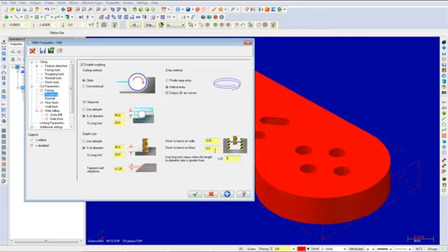I will now explain a few of these parameters. Cutting method allows you to set the direction which the tool travels in. XY step over sets the spacing between passes in the X and Y axis for the FBM generated toolpath type. Use defaults uses the XY step over defaults defined for the FBM generated toolpath type either from toolpath.defaults file or from defaults in the tool definition.